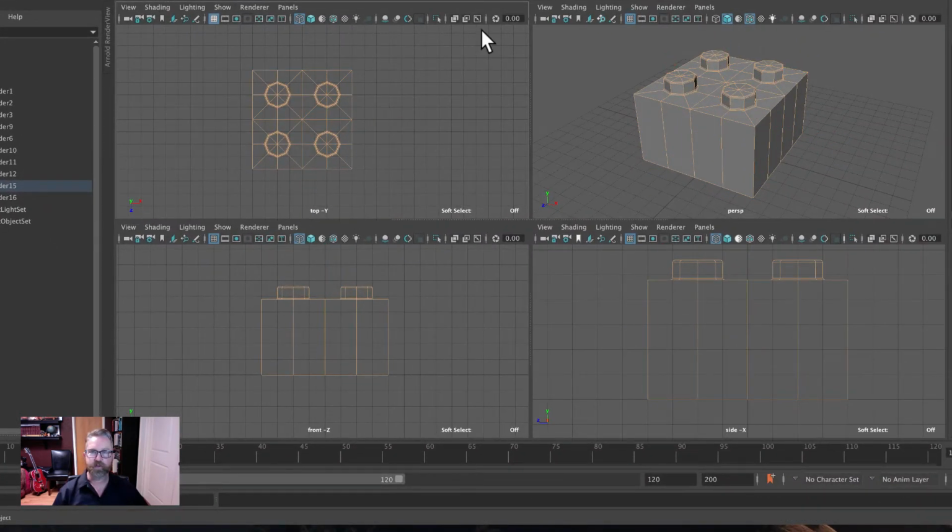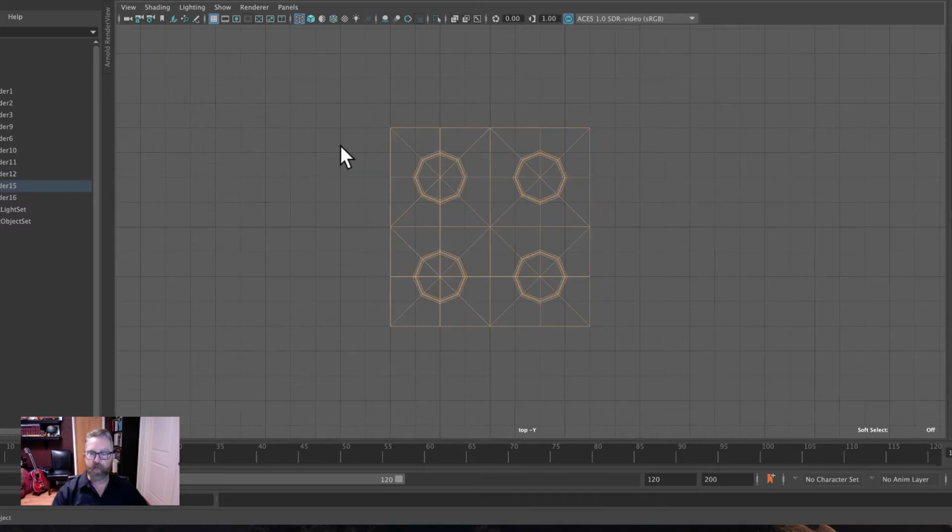All right, and we can use our latest technique for selecting the exterior edges, and we begin this process by selecting all of the edges initially. So just a big bounding box selection around everything. And in each of the orthographic views, we'll create a Control bounding box deselection. So take note, I'm selecting all of the edges within the square, or within this cube, right?